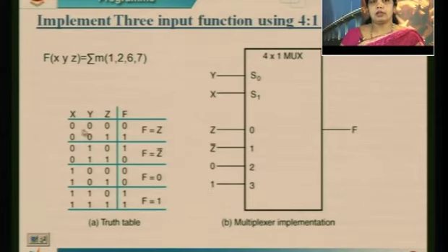You can just see over here 0 0 represents the first input, I0. So that I0 is nothing but Z, which I have given. So 0 1 is I1, where I have changed this to the map entered variable. Now my map entered variable is Z bar. So I have connected Z bar here. So coming over here, 1 0 represents I2. What will be connected for I2? It is logic 0. Similarly for 1 1, it is nothing but I3.